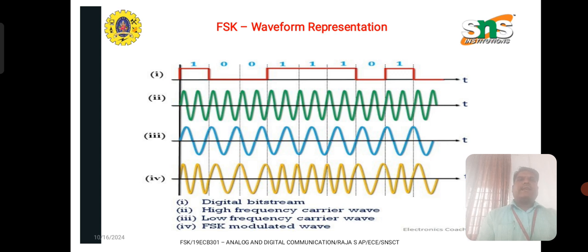So, as in ASK, FSK also has a concept. That concept is, whenever the bit is 1, it will automatically change into the high frequency. Whenever the bit is 0, the FSK will automatically change into the low frequency. These kinds of techniques are applied in some optical fiber communication methods.